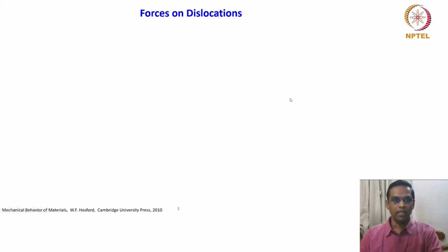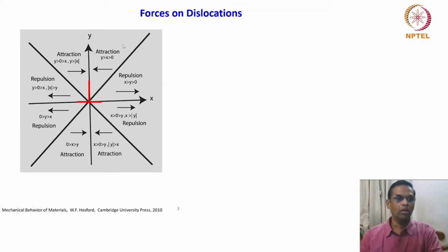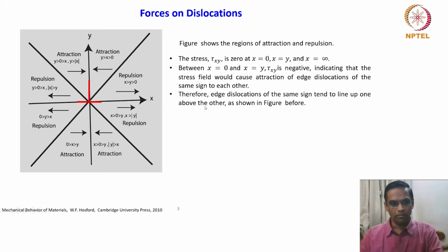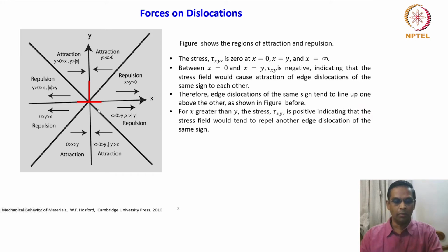We also looked at the stress field in this form, which clearly demonstrates attraction or repulsion in the fourth quadrant with respect to the x and y coordinates. This is very important to recollect, because depending on the stress field of the dislocation and the stress field in the solute environment, the interaction energy is decided.